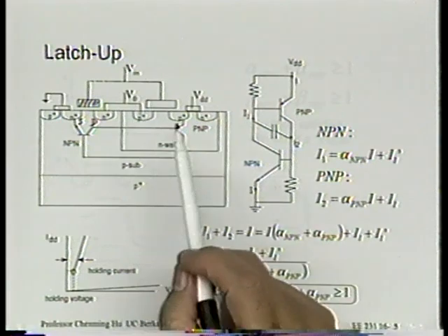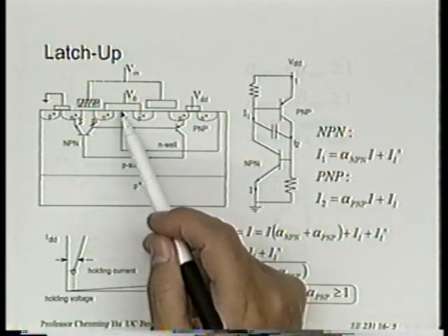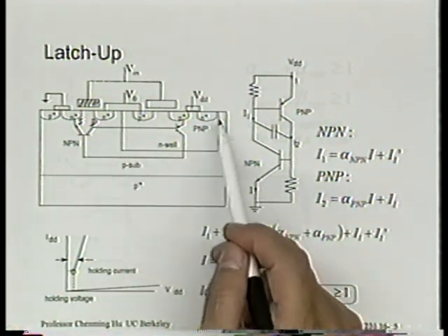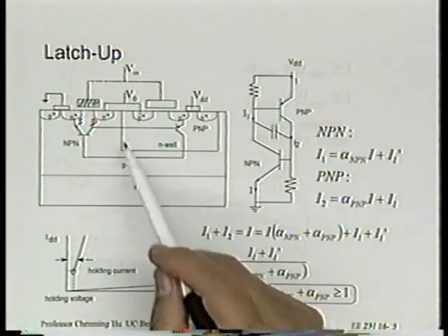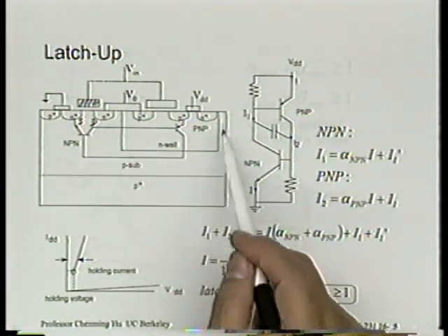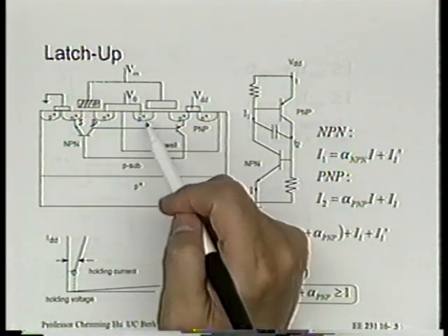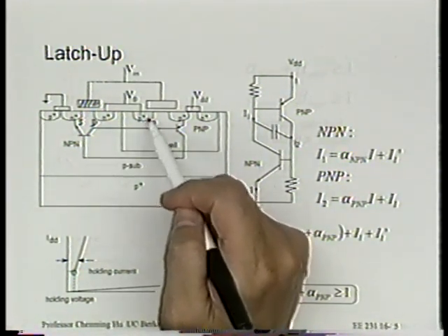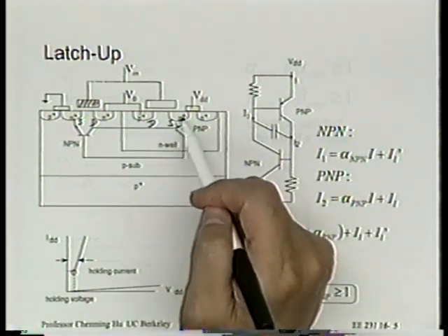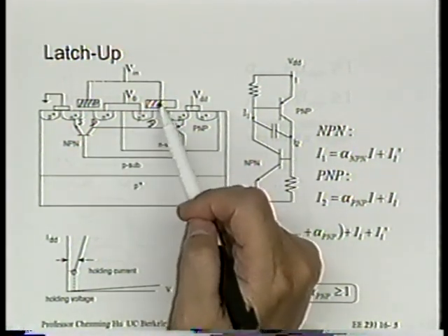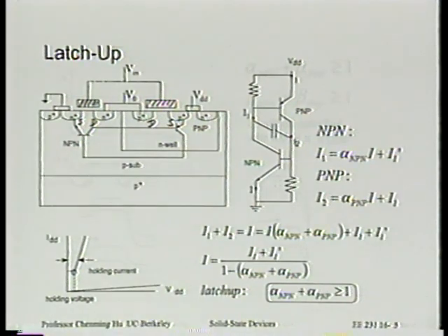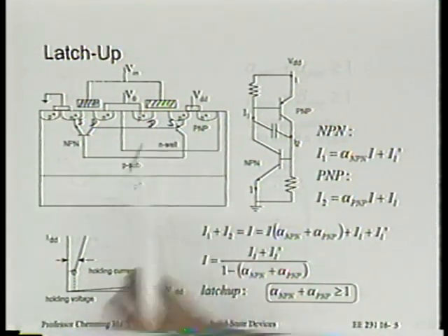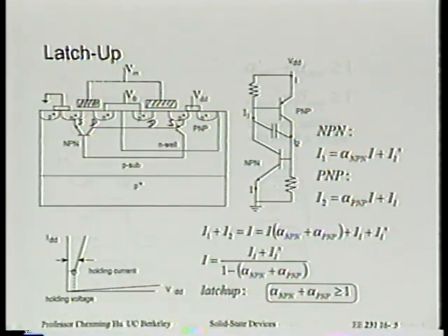To make a P-channel transistor, we first diffuse an N-type well into the P substrate. After we have made the N well, then we can create a P plus drain, a P plus source, and a gate for the P-channel transistor. So we now have a P-channel MOSFET.